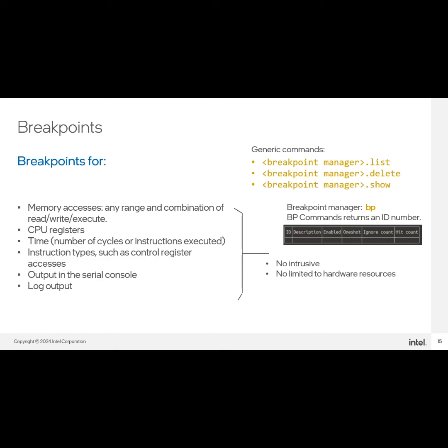The Intel Simics Simulator can set breakpoints on code and data. Unlike most debuggers, the simulator breakpoints are not limited by what the hardware can support. For example, there is no restriction on the number of read-write breakpoints, also known as watchpoints. This makes it possible to narrow down the location of difficult bugs by rerunning the same simulation run as many times as you need.